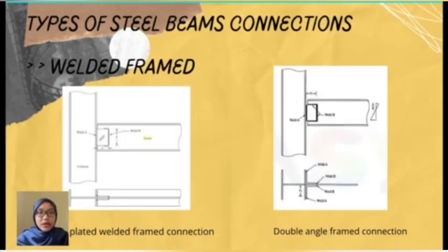Moving on to welded frame. Like the other two types of beam connections, various sizes of welded frame connection with their capacities are available and provided by codes. The weld of the connection is subjected to direct shear stress and stress caused by loads on the beam that affect weld pattern. So these stresses are required to be considered.